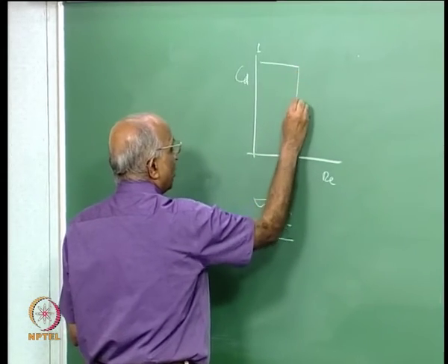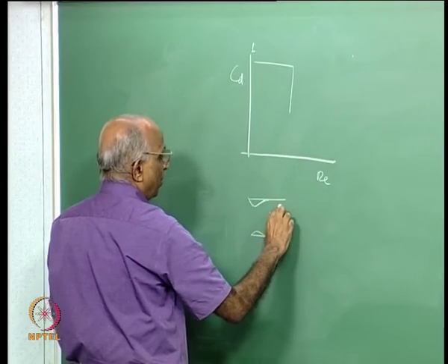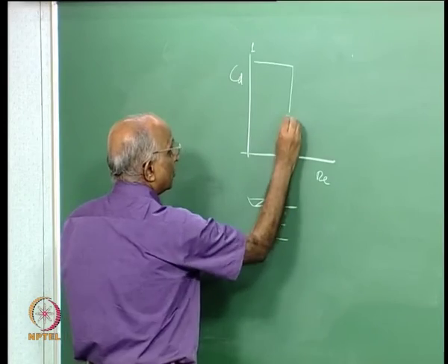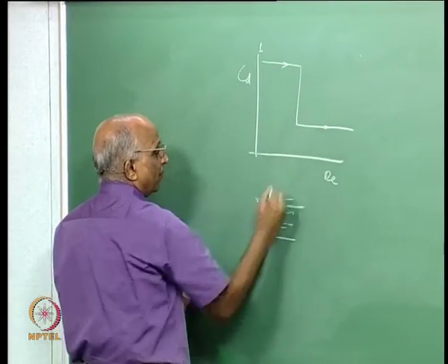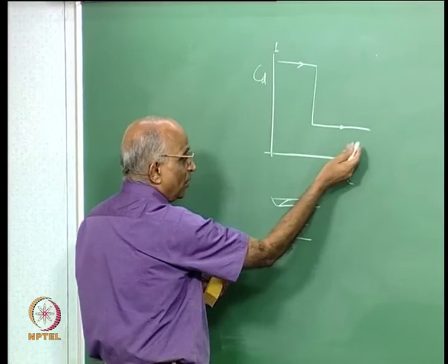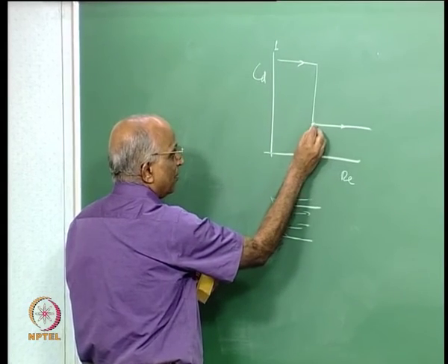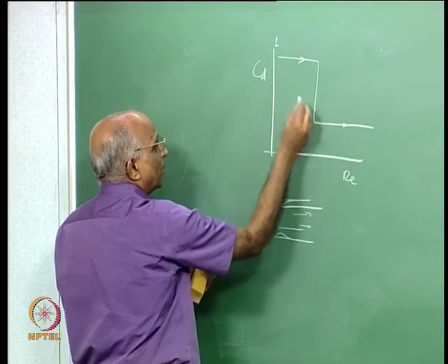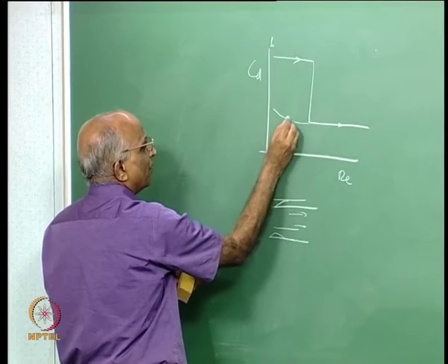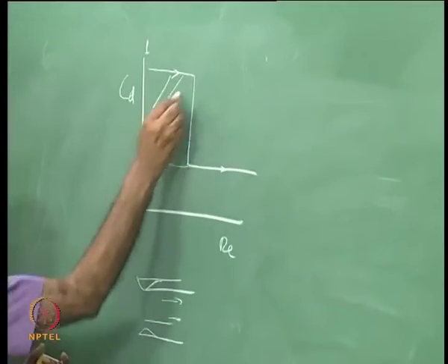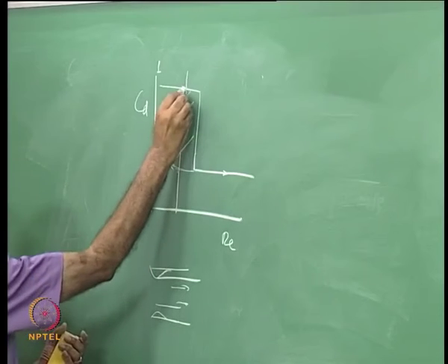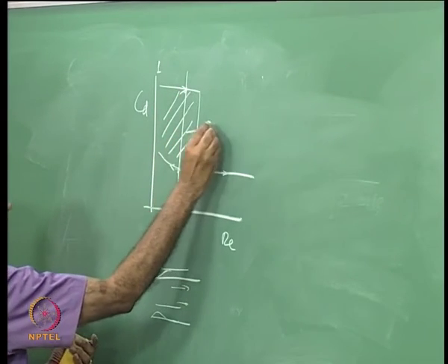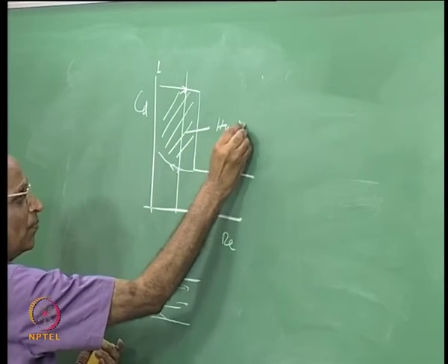But all of a sudden, when the pressure of the liquid drops to vapor pressure, the flow separates and comes over here. This is my forward direction. After doing this, I want to throttle it back, I reduce the pressure, it does not go back over here, it goes back like this. That means I have a zone which for the same value of Reynolds number can give me 2 values of CD, and this zone is known as the hysteresis zone.